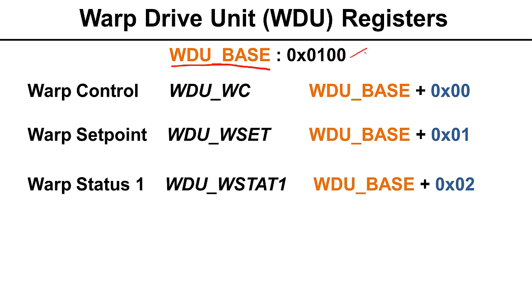And this is very common, where we don't necessarily specify the address of each register. We're going to specify them as a base address plus an offset. And the reason we do this is that in some cases, some peripherals, there may be more than one. So we just document the offsets, and then the system engineers who made the chip might put more than one copy of the same logic. So this is very common to see this base and then offset notation. And in a future video, when we talk about C data structures, it actually makes perfect sense why they do this, because there are some really cool ways you can use to program it.